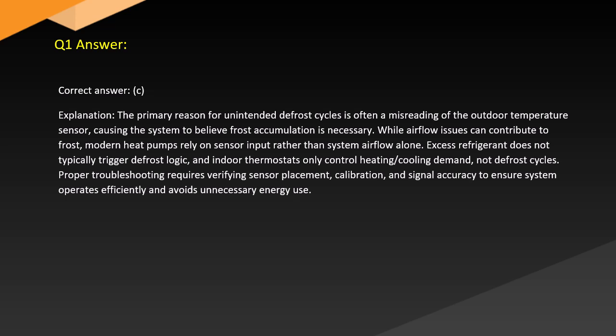While airflow issues can contribute to frost, modern heat pumps rely on sensor input rather than system airflow alone. Excess refrigerant does not typically trigger defrost logic, and indoor thermostats only control heating and cooling demand, not defrost cycles. Proper troubleshooting requires verifying sensor placement, calibration, and signal accuracy to ensure the system operates efficiently and avoids unnecessary energy use.